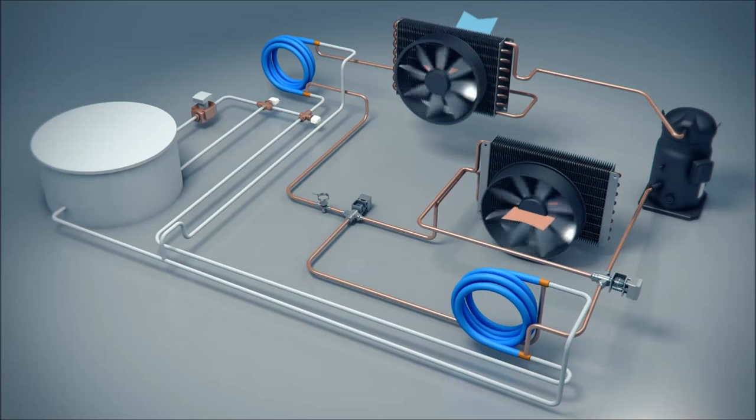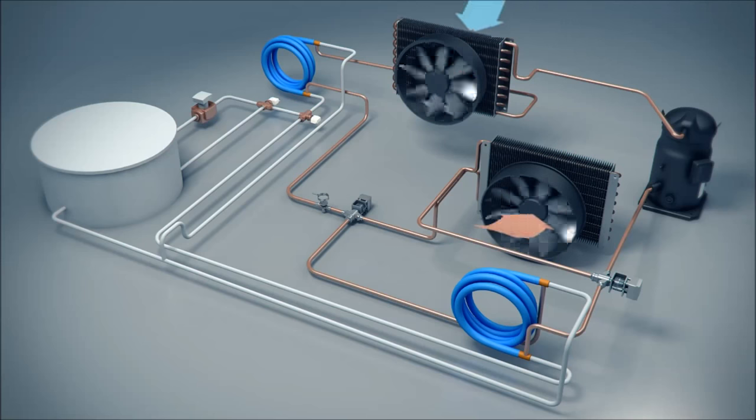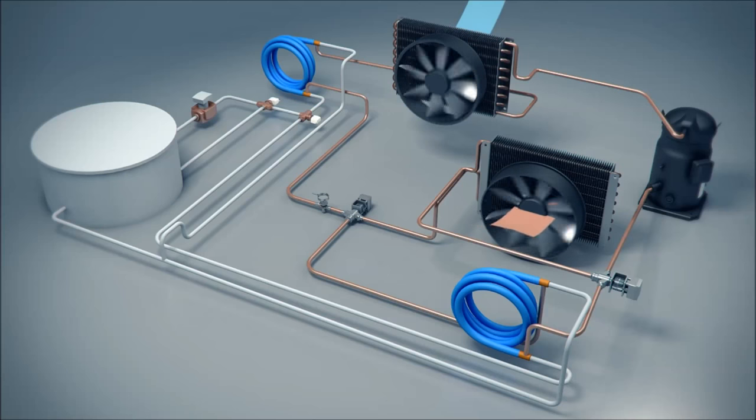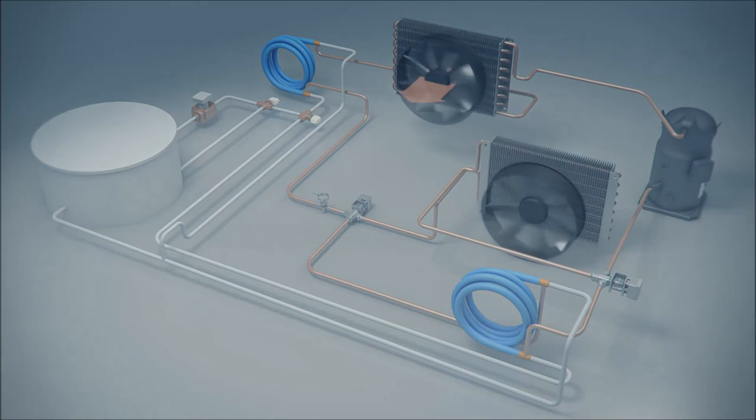The AC Companion stabilization loop is engaged upon demand for refrigeration, when space cooling and ambient temperatures are near their peaks, typically between the hours of noon and early evening. The AC Companion charging loop facilitates the operation of the AC Companion stabilizing loop by charging the ice storage vessel. It operates when the ambient temperatures are near their lowest point, typically late at night or early morning hours. The AC Companion stabilizing loop and the AC Companion charging loop are not permitted to run simultaneously.